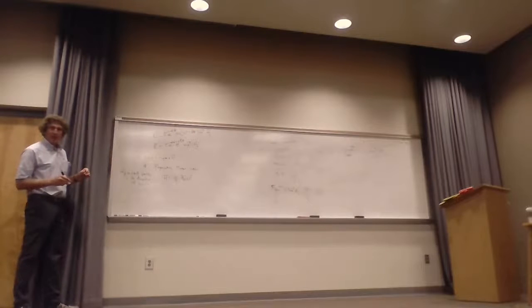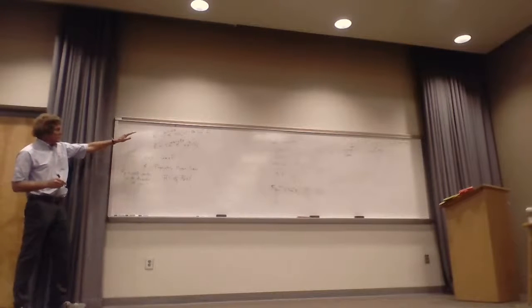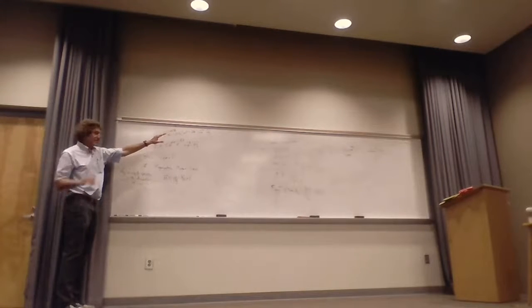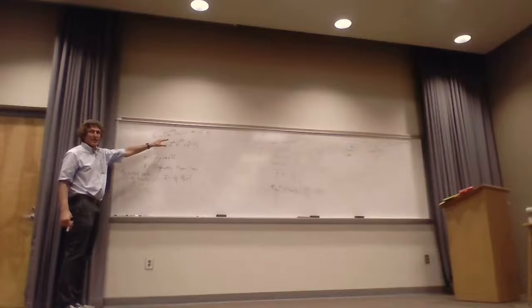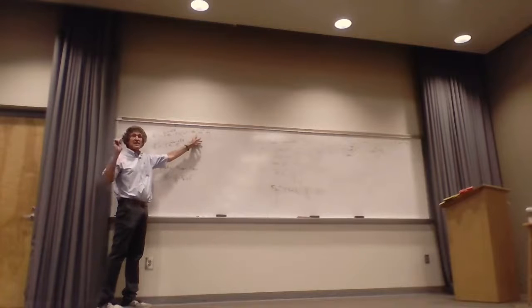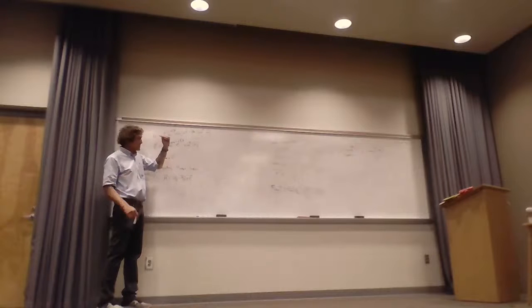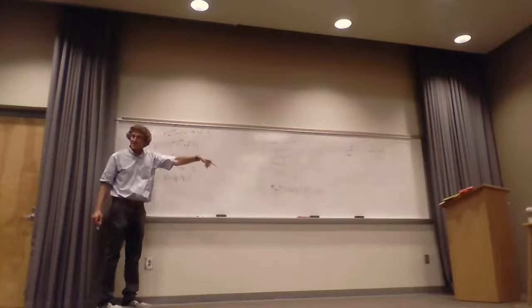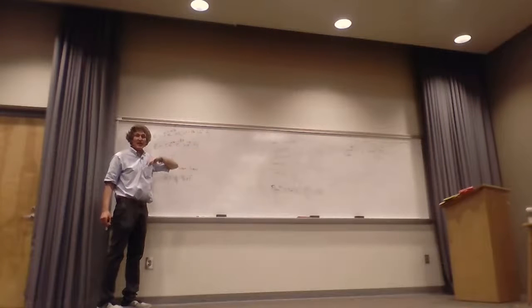Okay? Now, I want you to look at this. Which way is that wave propagating? Which way is it moving? How do we know? It's the coefficient of this, right? If there's a minus beta z, it's going in the plus z direction. If it would be plus beta z, in the minus, right? And the way you always get this is you take a look at the coefficient of the actual spatial variable. That coefficient is the magnitude of beta. If it's a minus sign, it's propagating in the plus direction. If it's a plus sign, it's going in the minus direction.